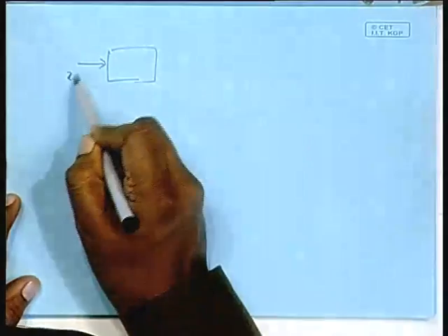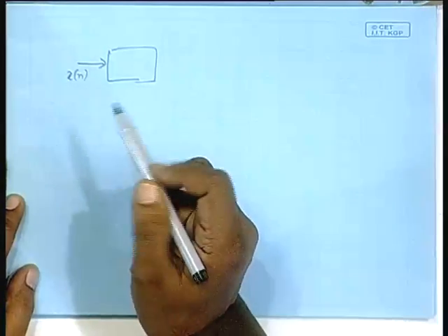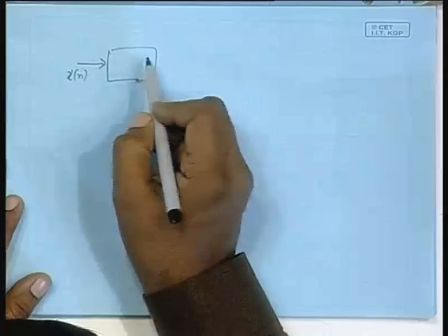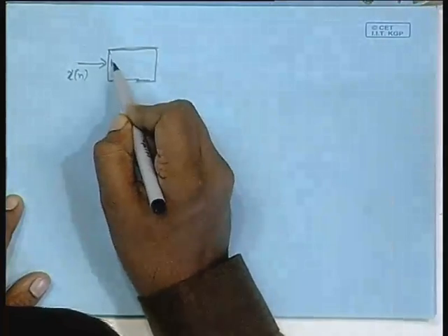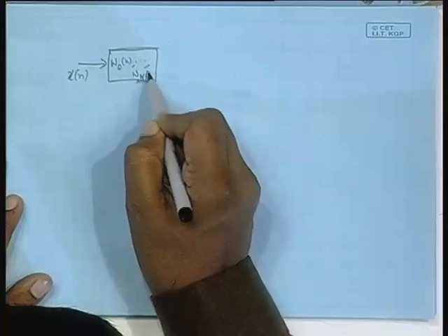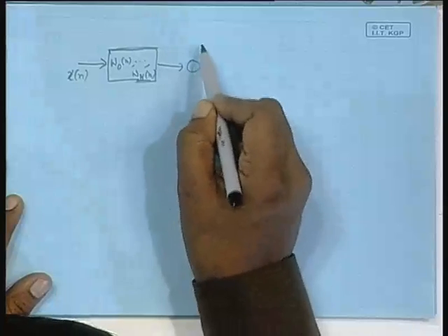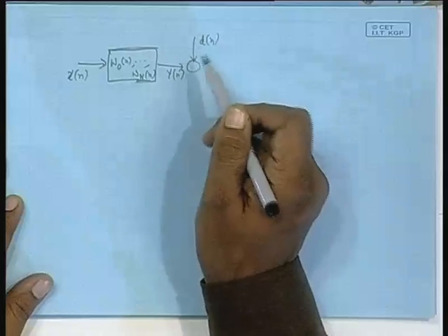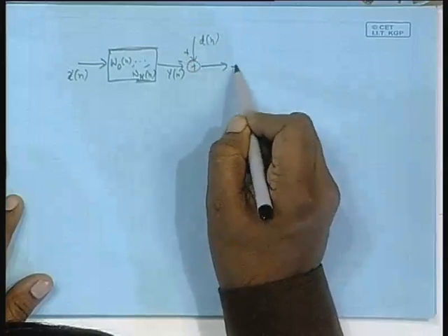We had just concluded with the LMS algorithm for the complex case. So, let me just quickly go through those steps. There we had x n, a zero mean complex valued random process, and the filtering problem was this: w 0 n, dot dot dot, w capital N n, d n, y n. D n also is a zero mean complex valued random process. If you subtract, the error is E n.